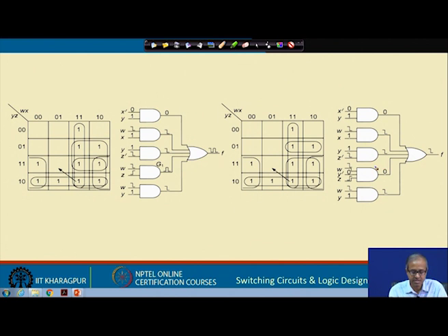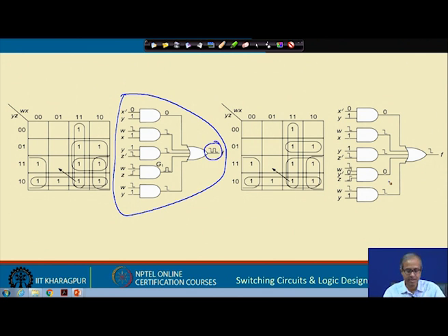This was your original implementation, which was resulting in a dynamic hazard in the output. Okay. Now, here what I am doing, instead of this W z, here I have modified this. So, with this modification, you see in the output I am having a clean transition. So, the idea is this, you must prevent some of the transitions from happening. If you can do this, then the dynamic hazard in the output will be avoided. Well, I am not going into too much detail of this, just trying to give you a basic idea that this is how it is done.